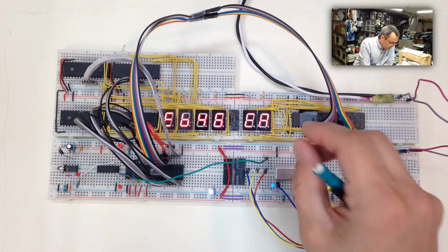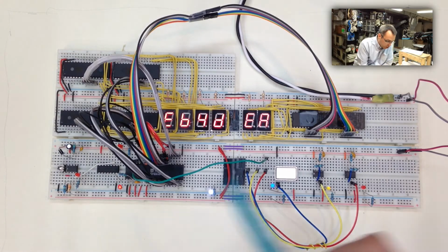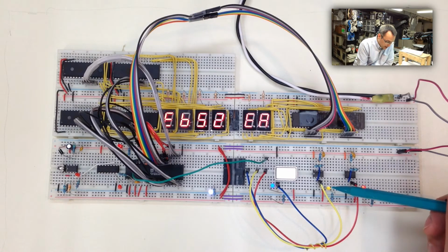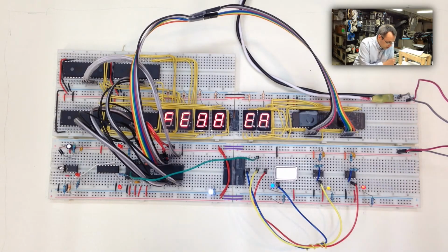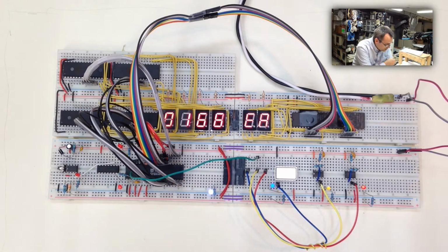Now, let's play around with the speed. So we're running at approximately 1.6 hertz. But let's pop the guy over to here and let's turn it up to, I don't know, 150 hertz and see how fast it flies. There we go, and it is zooming off to the races. And you can see some of the LEDs are blinking a little weird. I must have some sort of signal isolation issue, or I might need a decoupling capacitor put in here somewhere that I forgot.